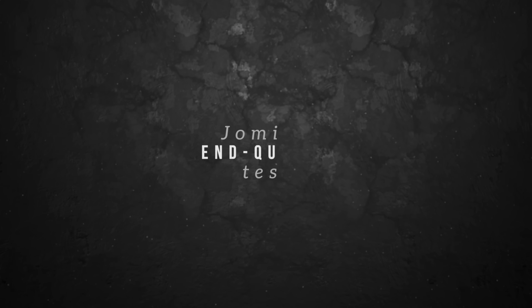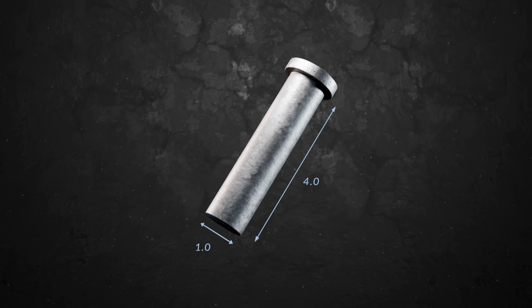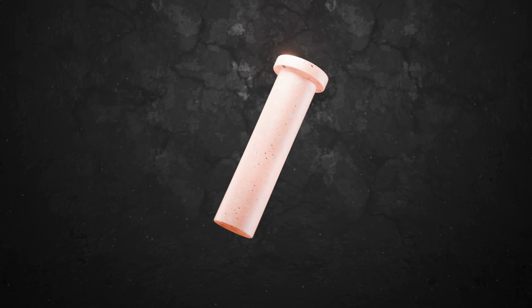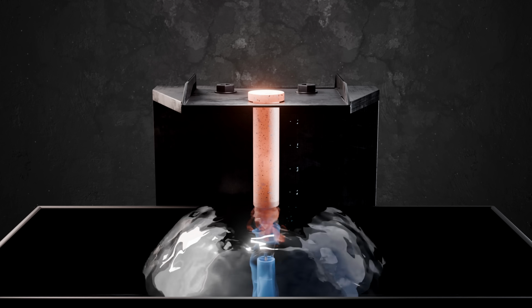The Jominy end-quench test is the standard method for measuring the hardenability of steels. It involves heating a cylindrical steel sample that's 1 inch in diameter and 4 inches long until it's fully austenitic. One end of the sample is then quenched with a standardized water spray setup, creating a controlled cooling rate that decreases as you move up the sample.